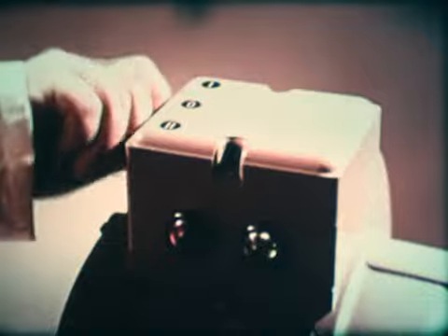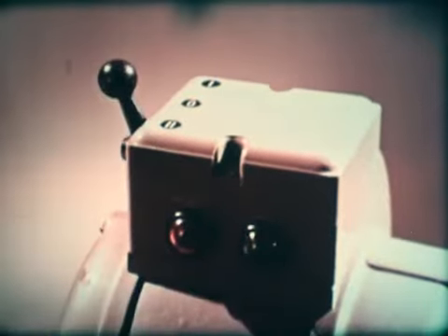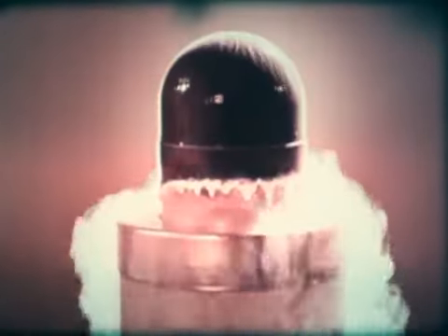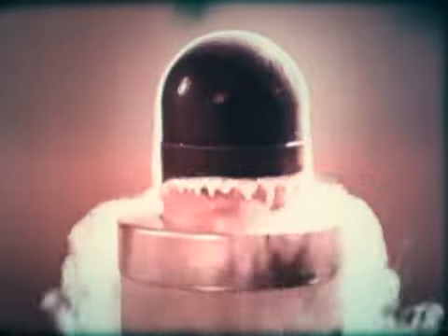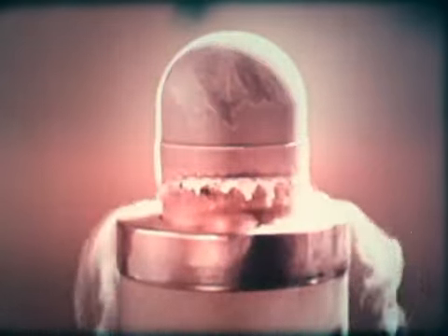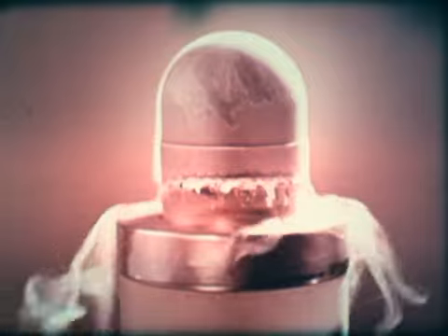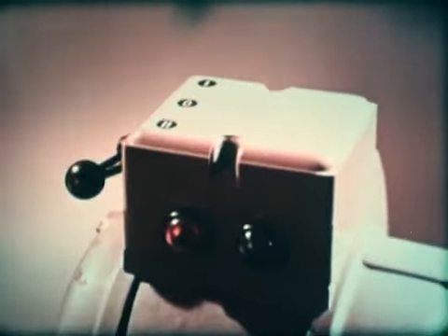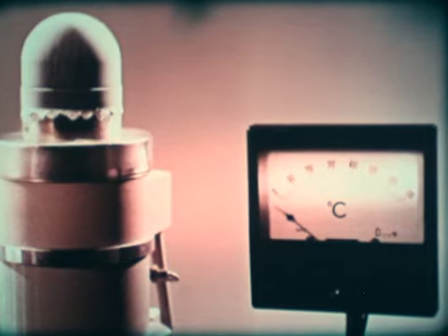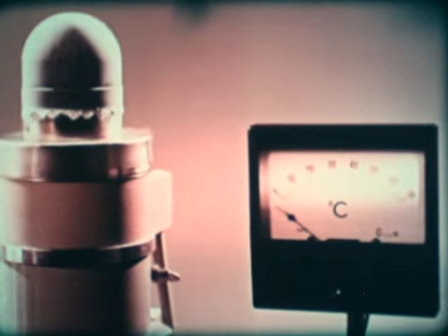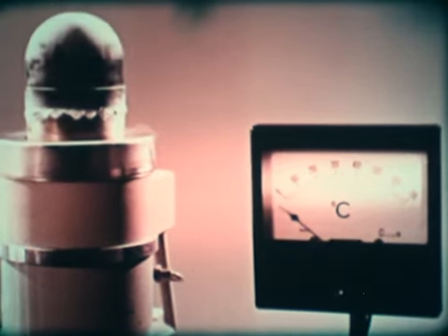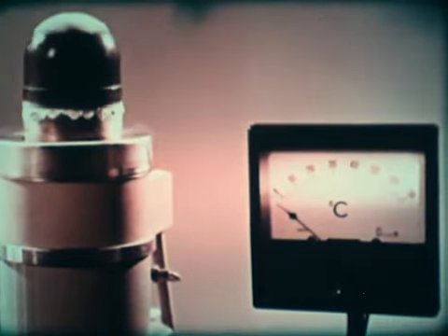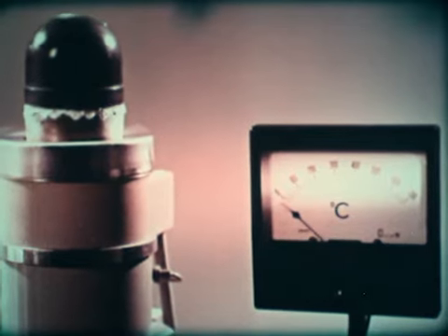The cold that is stored in the head may be used to obtain mechanical energy. When the electric motor is switched off, the machine itself will start to run, but in the reverse direction. It acts now as a cold gas engine as long as the head remains cold enough. Before the cold gas engine comes to a stop, the electric motor is switched on again to keep the machine running in the reverse direction. Therefore, the head will continue to be heated up, and the machine now operates as a heat pump.